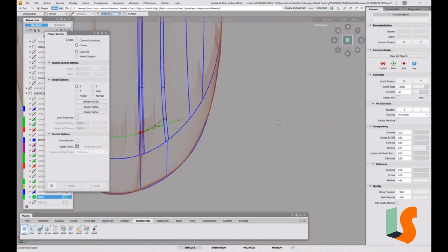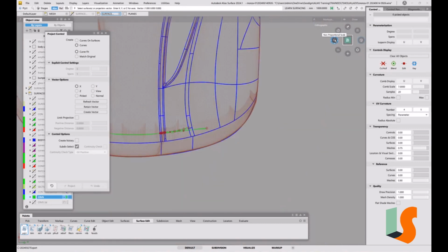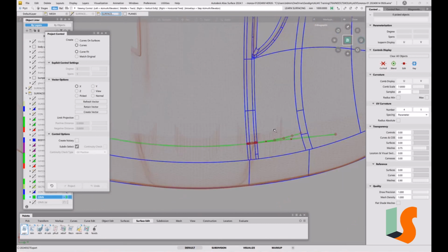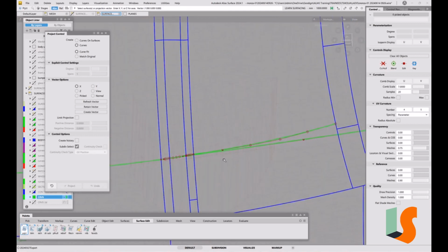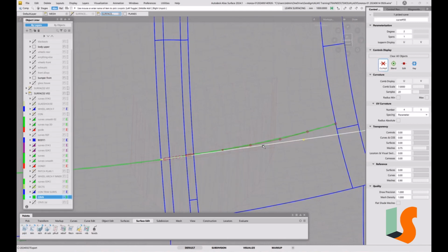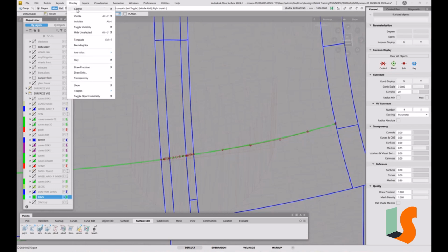Take non-proportional scaling off. So it's slightly different. It's not a pure offset in this area from this front edge in that view. Like I say, it's going to deviate from the mesh. We can then rotate that in 3D. Let's just get rid of that for a second. I'm just making it invisible, and we'll take all of the CVs off.